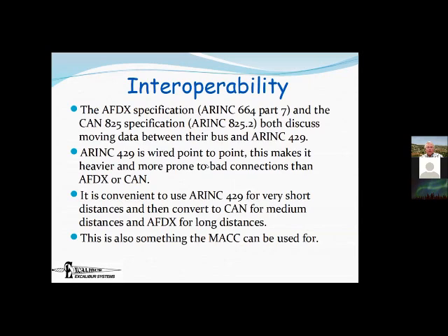Okay, so now talk about ARINC-429 does not work in a vacuum, or at least not anymore. It used to be pretty much the only game in town on civilian aircraft. Today, the larger aircraft are using AFDX, which is Ethernet based, or they're using CAN bus. And so you've got some devices that are CAN bus, some devices that are AFDX, and some devices that are ARINC-429. And there are various reasons why you would use one more than the other. And therefore, you need to translate between them. That's exactly the sort of thing that a Mac can help with.